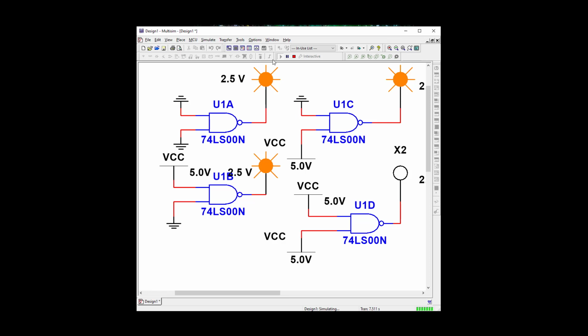And let's try it. And open them up. So we have a 5-volt high and a 0-volt ground. Not even close to the nominal values that we normally get. So nominal, a high is about 2.4 and up. Okay, that's why they set it 2.5. So a valid high will be from 2.4 to 5 for a TTL device. And this one is going to be from 0 volts to 0.8 volts for a valid low.